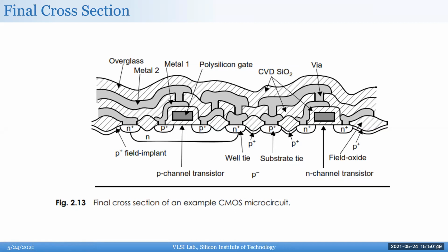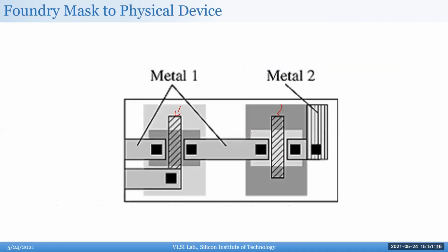And when you start doing a DRC for larger chips, you'll see all these density rules. You have to have a certain amount of metal in every area of your chip. You cannot have a millimeter square of area and just have one end metal 3. If you don't have it, you have to fill it with metal, just floating metal, because otherwise this whole polishing process will just fall apart. And that's true for all fine line technologies. For the old ones, it's not as necessary.